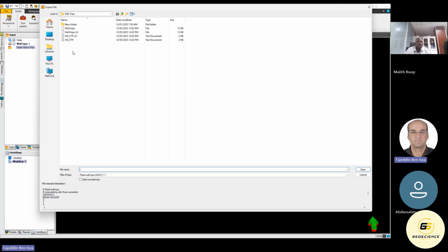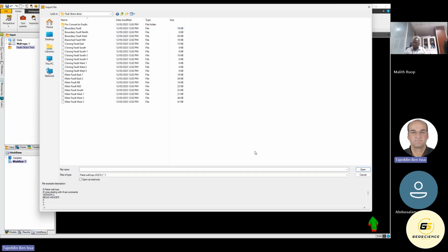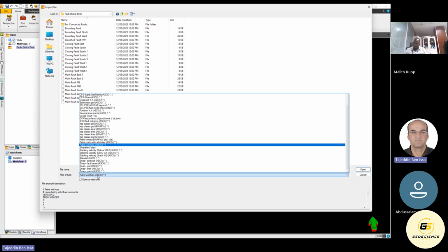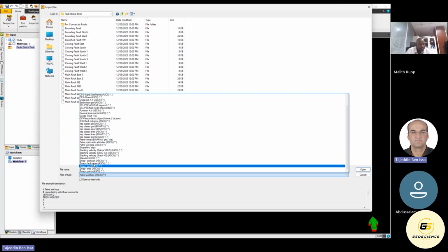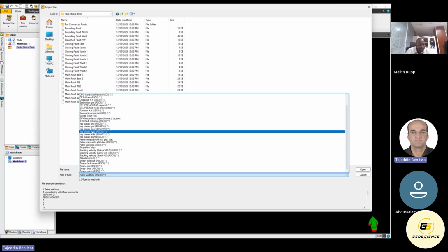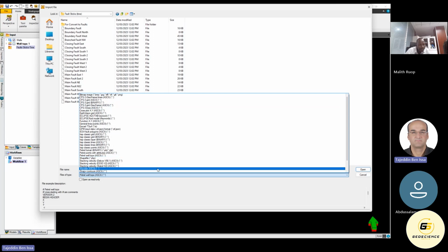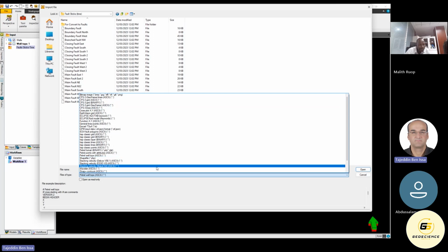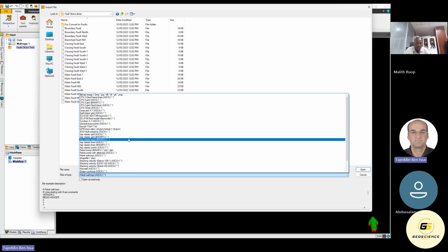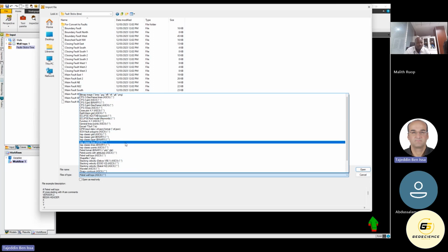So we go to the faults folder, fault sticks in time. I click on it. I choose the Z map lines because the format of the faults can be several in Petrel. You have all these formats you can deal with. You have the Z map, you have the Eclipse, you have the CPS-3. You also have the Charisma. When you work on seismic interpretation, you will also have the Charisma fault format.